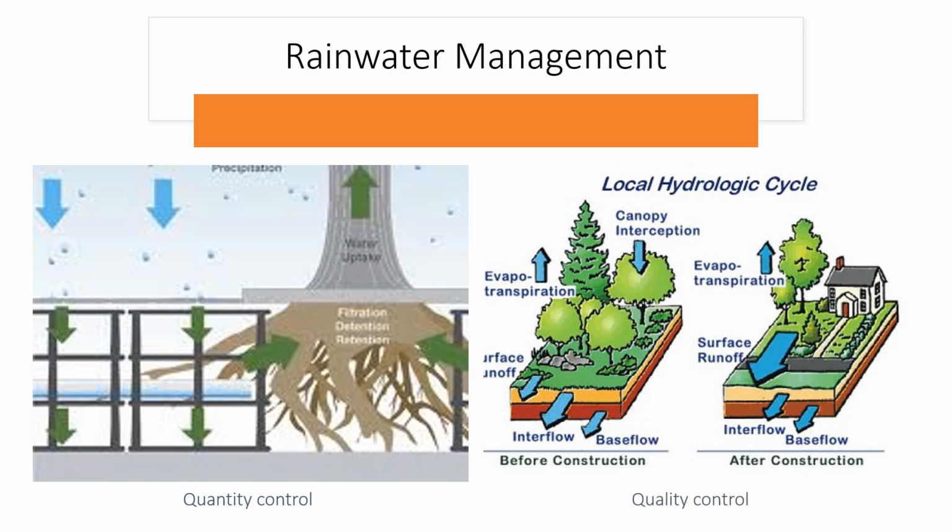You can increase vegetated roofs and porous pavements and grid pavers. You can harvest rainwater by adding a rainwater cistern to capture water from roof downspouts. And from a non-structural standpoint, you can use rain gardens, pervious pavement, and vegetated swales.